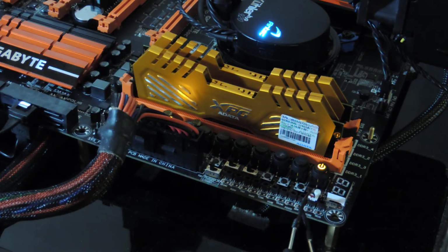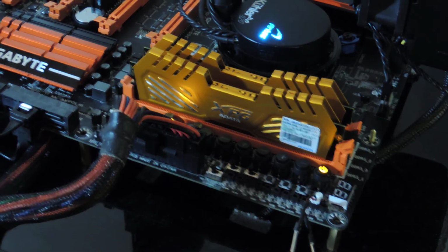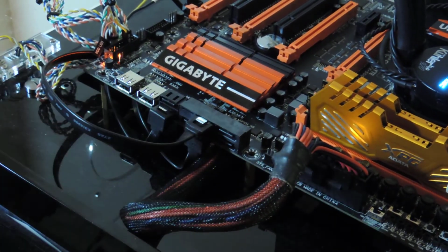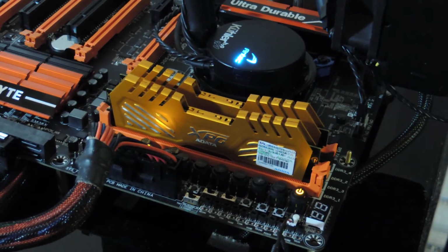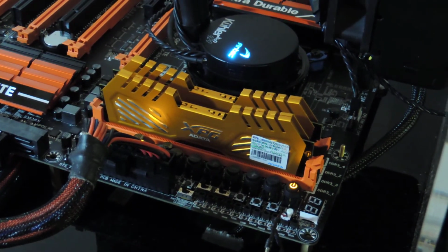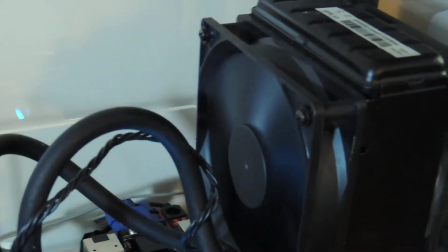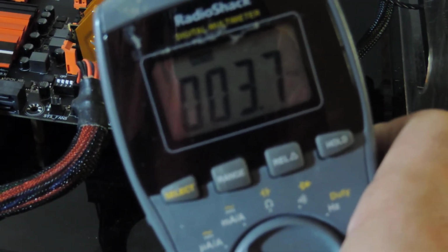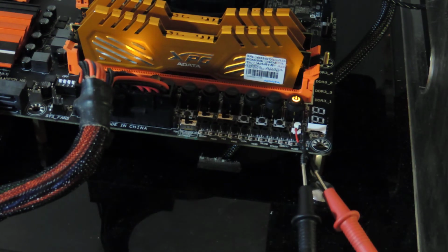See, nothing comes up on the post screen. It's not supposed to, but you see everything powered up. The light came on for the BIOSes. I can hear my hard drive spinning up. The button lights up. Fans are working. You can hear it, or you can just see the fan working, right? And the system is off. You can see vCore is also 0, right? Basically 3.7 millivolts, just residual charge.